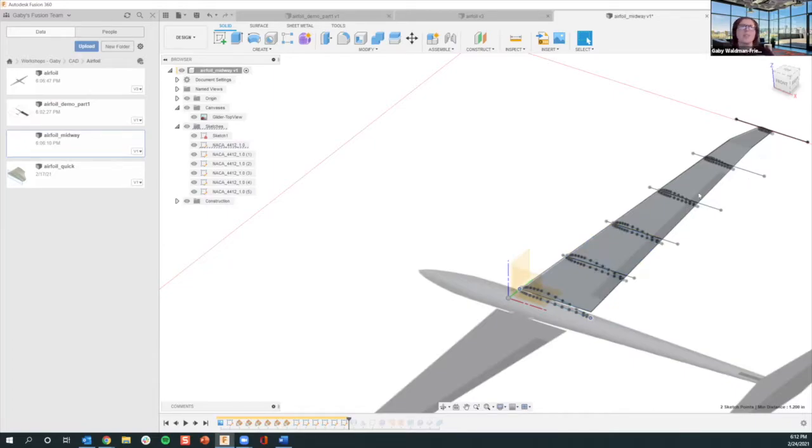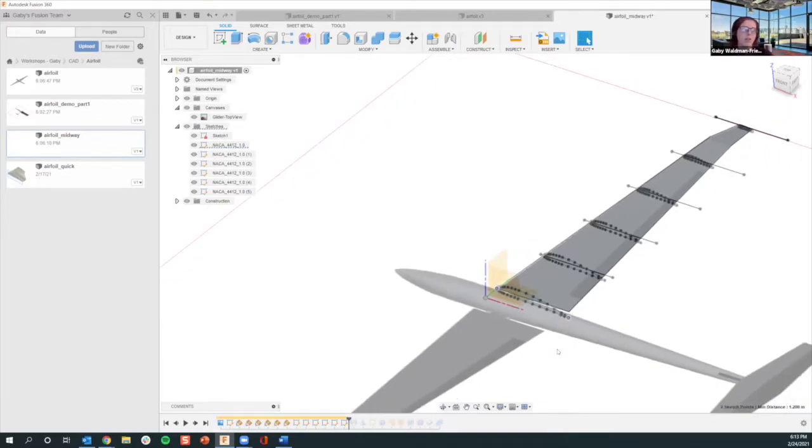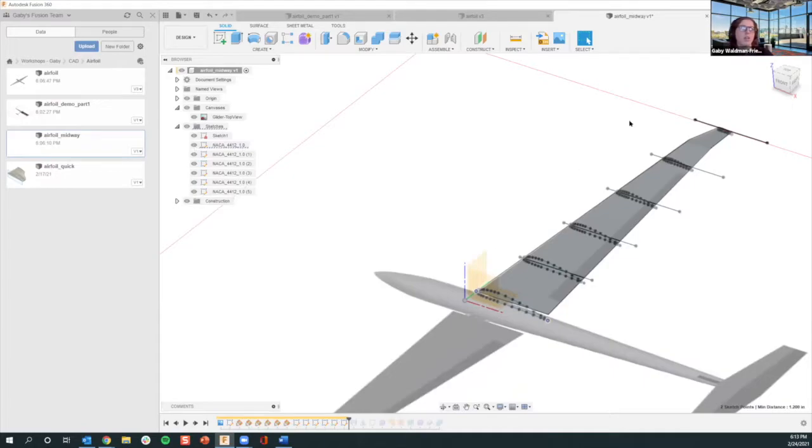You could copy and paste and then scale down, but that scale down is going to be a percentage, not a specified chord length. So, for example, I could have copied and pasted this one, moved it to the next surface, but then I would have said, okay, scale down 20%, but that wouldn't have given me an exact result. So it's not a great solution. That's why I made all these planes and imported it each time onto the plane with the scale. And I was able to do that with a plugin, which I talked about last time. So now the next step is to make a loft between them.